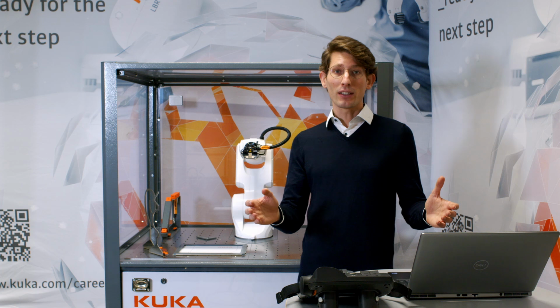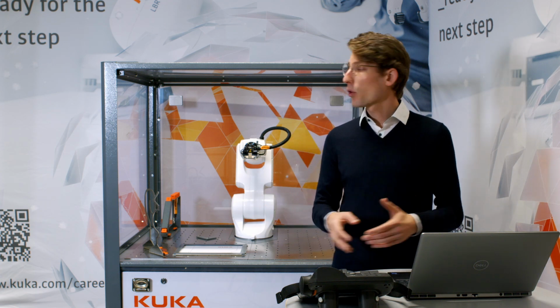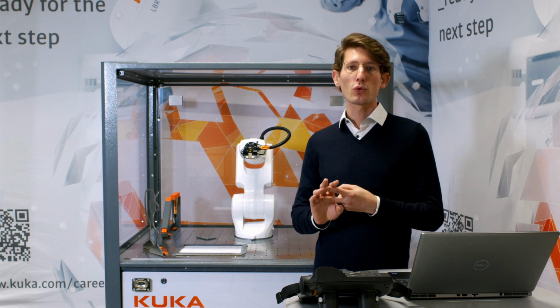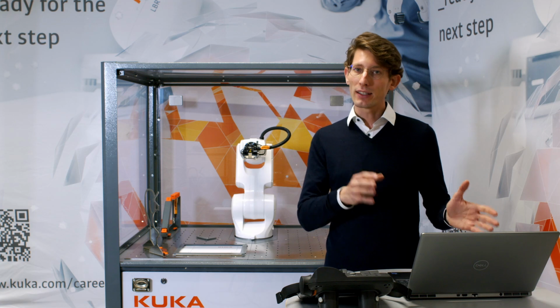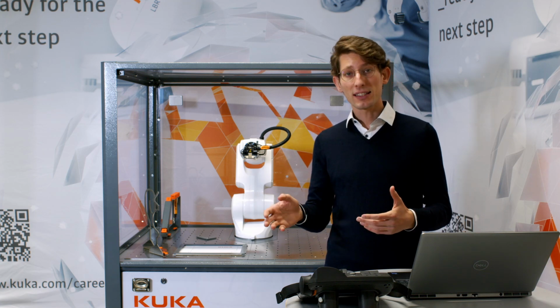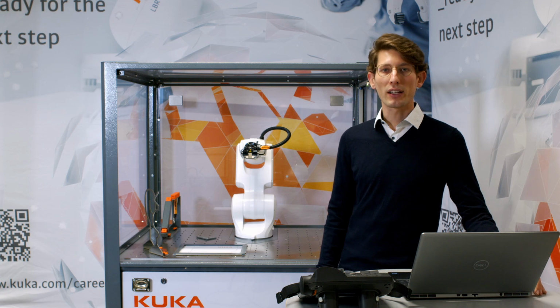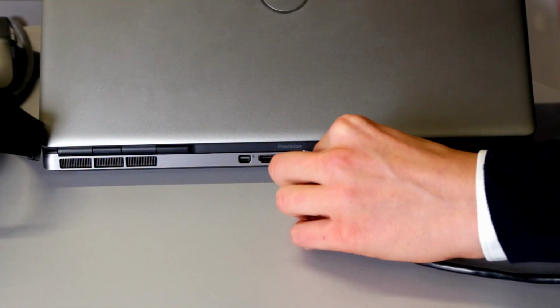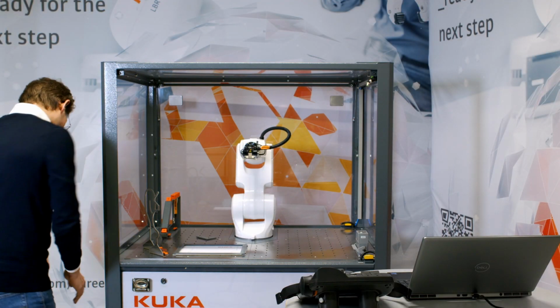Now that we've done the offline programming, we can start by connecting KUKA.Sim with our robot. So for this, we have two options. The first one is if your robot is connected to the internet, you can find it over the IP address, or in this case, we're going to use the Ethernet cable. So I'm going to plug it into my computer and into the robot. First that, and second into the robot.